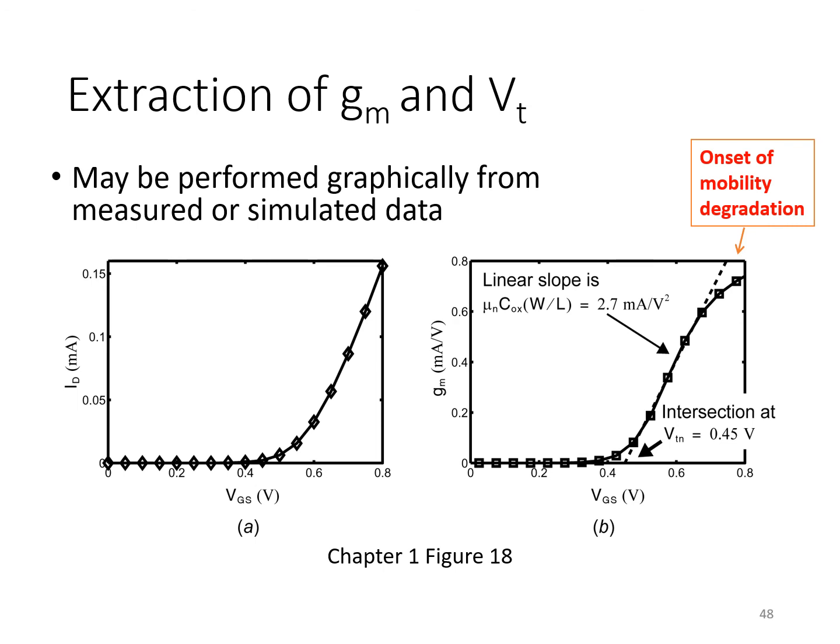You would expect a square law model, and you can take the derivative of that, and you end up with a plot on the right of small signal transconductance versus VGS. From that plot, you can find the point where the linear part of the curve intersects the abscissa, and that intersection will allow you to estimate the threshold voltage.